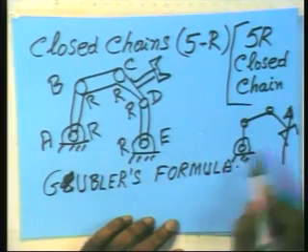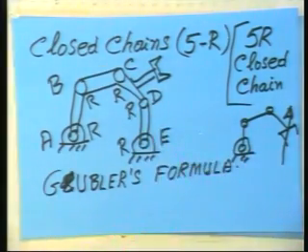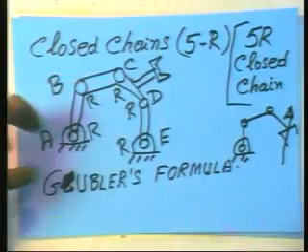Here the motors have to, because you have got two things coming in parallel and supporting the end effector. In this case, there are two parallel paths from the end effector to the ground, whereas there is a single path here from the end effector to the ground. So this tends to be stiffer. Though the work volume of the parallel chains is not as much as that of the serial. The work volume available, that's one of the problems.